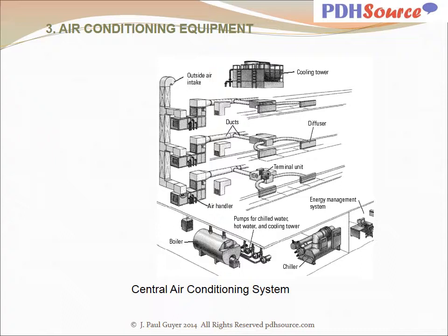You also see some ductwork there that is not terribly well drawn in this illustration. What that ductwork is doing is, when the return air is returned to the fan room, a certain percentage of it, say 15 to 25%, is forced by fan pressure outside through an exhaust duct and is exhausted to the outside of the building.